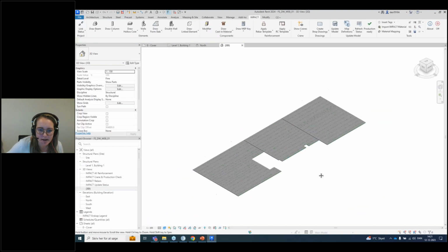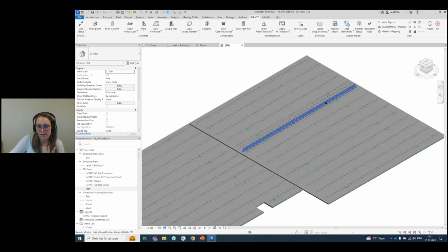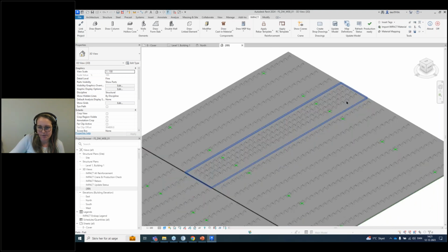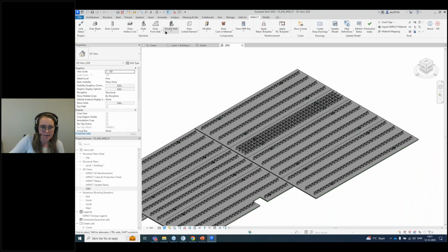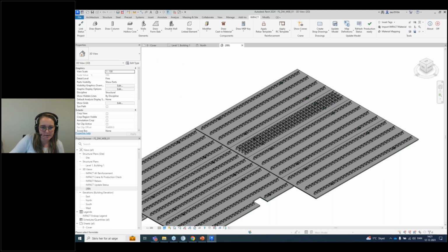Here it is. Here we have our slabs, and we start the edit command, because you can see I've said 4 girders, but probably that's too much for this one. So you can edit that. You can go to Edit Formslab, which you can find here. Select the slab, right?